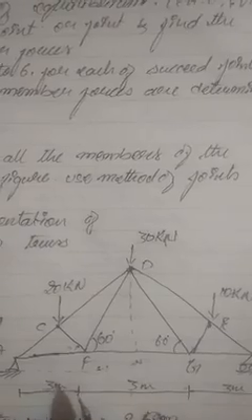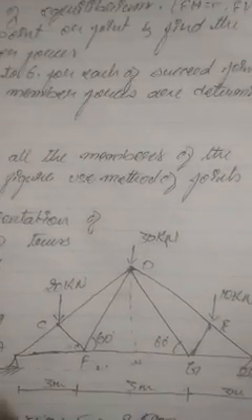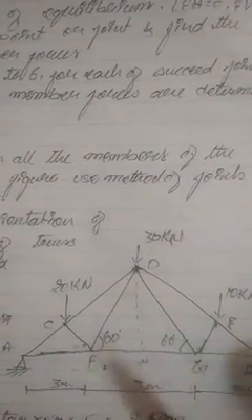First you have to select a point where there are three forces, where there are two unknown forces and one known force. Like that you have to choose, and by that you go further, finding the forces of the rest of the members. This is how the process moves forward.